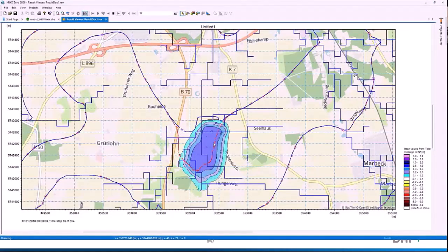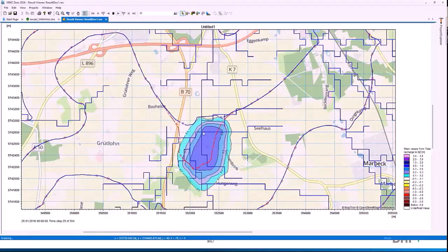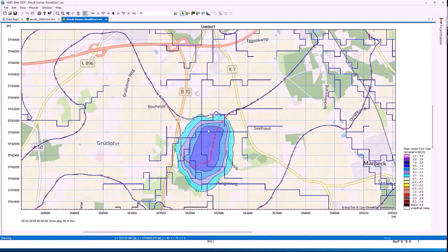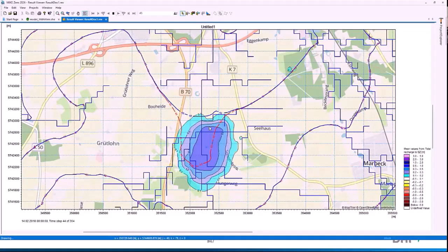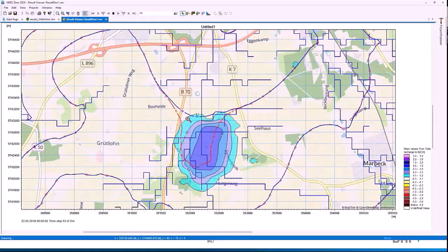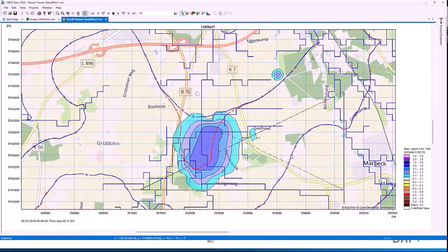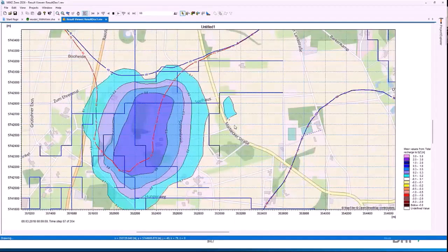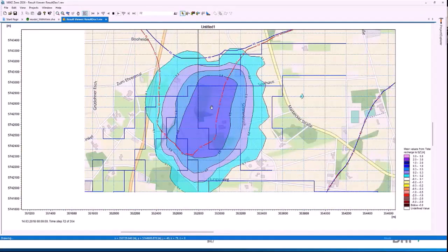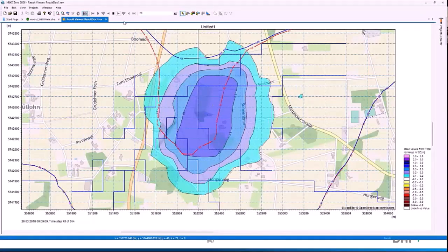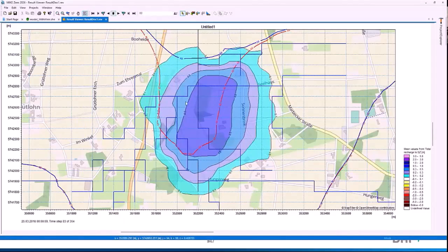And even visualize the differences. That means when the weir is pulled up, we now have a rise in the groundwater because less water is drained. And you can even see how the groundwater isolines would develop over time. And this was now a very detailed assessment, which we did for several locations within this big project.